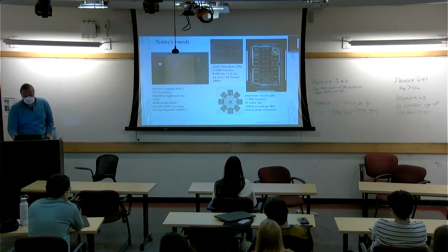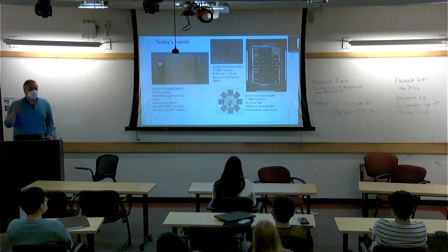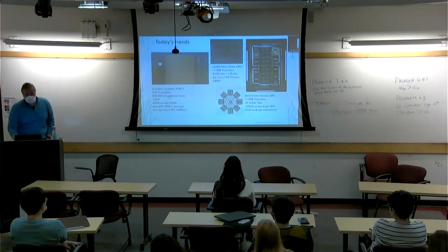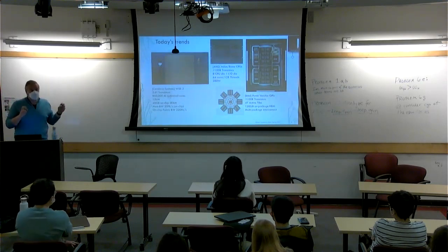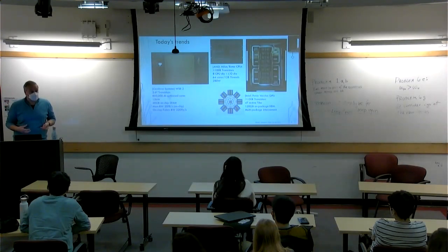And then an important thing for a bunch of these that are smaller is that you're starting to see board level networks. It's not enough to have one socket to do something, but because of really high demands, mostly AI applications, you need to think about how you are going to wire all this up at the board level and provide what types of connectivity and memory semantic fabric networks are good for the applications you're running. So you can see rings for, let's say, ring all-reduce, which is kind of the AI way for training to aggregate the gradient, or you can see all-to-all communication, things like that.